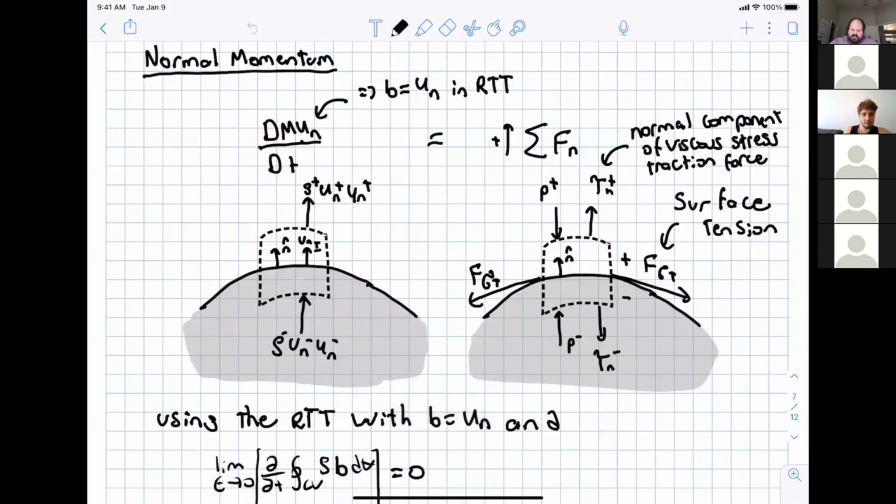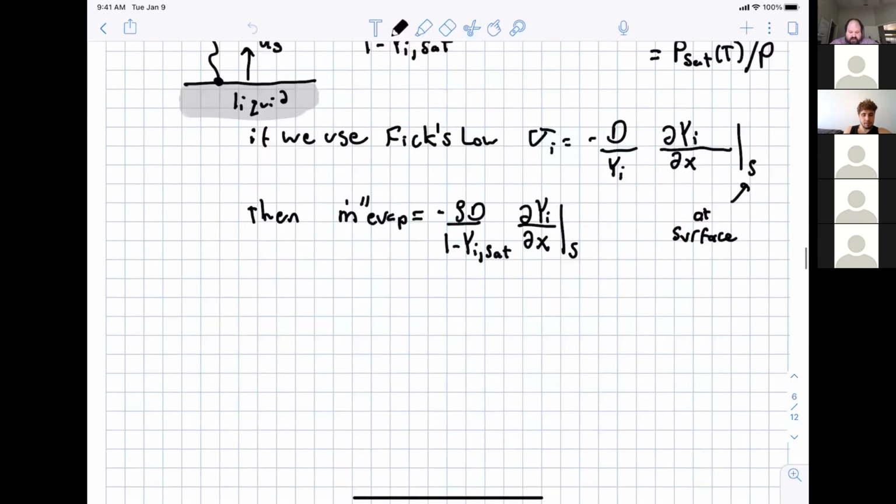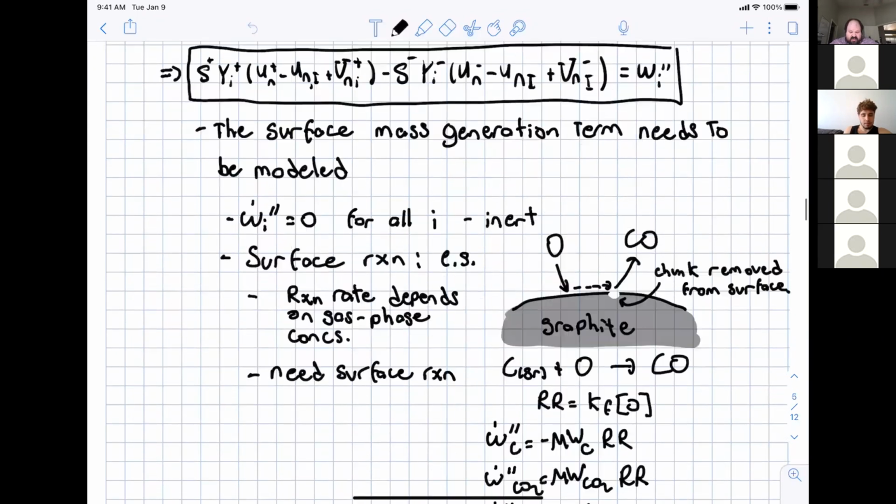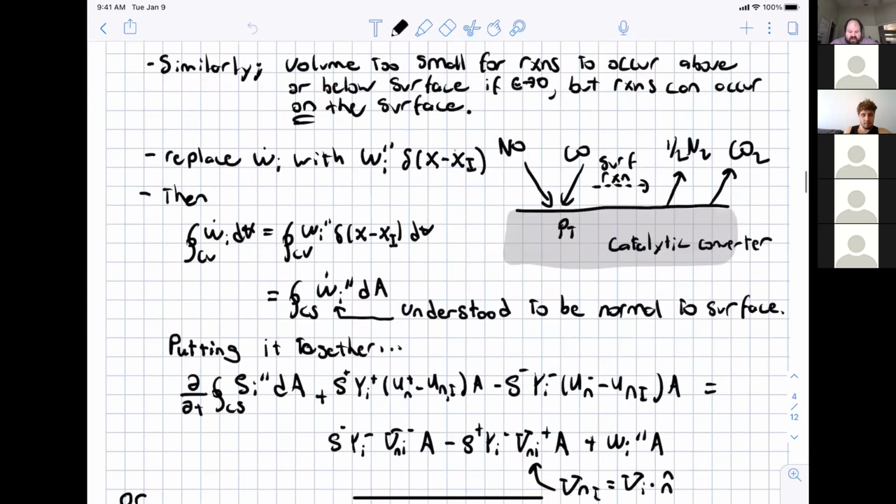Okay, so last time we were discussing interfacial boundary conditions, and we had discussed conservation of mass, and we had finished on discussing conservation of species mass, which is actually probably one of the most complicated ones to deal with, just because you may have no species mass fraction on one side of the interface and a species mass fraction on the other side. And so the species mass equation, the interfacial boundary conditions usually require the most thought out of all of them.